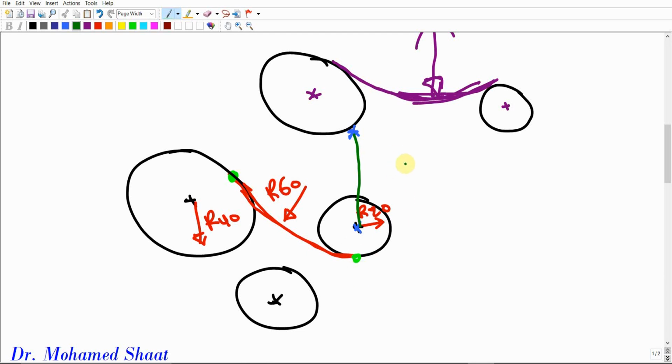If you try to connect a line between the two centers and this line does not go over the tangent point, you are going to subtract the radius of the circle from the radius of the curve, or the radius of the curve from the radius of the circle. In many cases, you're just going to subtract the smaller value from the bigger value, right?